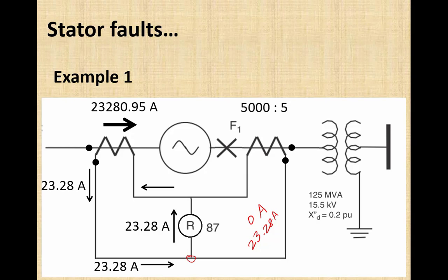And that sensitive value for such a differential relay will be either 0.1 ampere or 0.2 ampere, or at maximum it could be up to 0.4 ampere. So this is the normal pickup setting of a differential relay in this configuration, and this differential relay is known as an overcurrent differential relay. It makes its decision based upon the current through the differential branch.